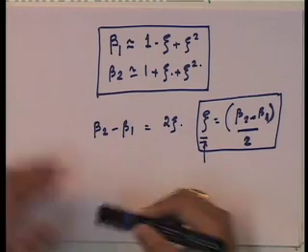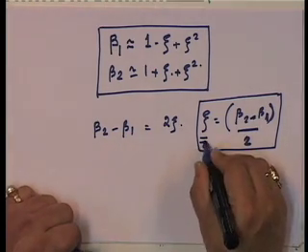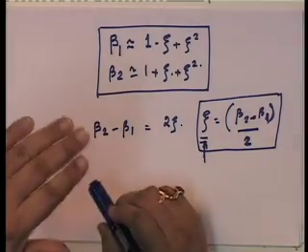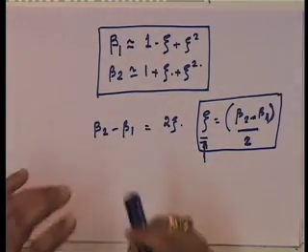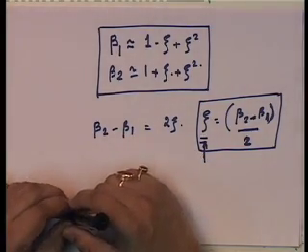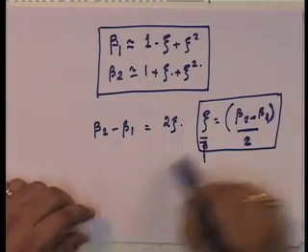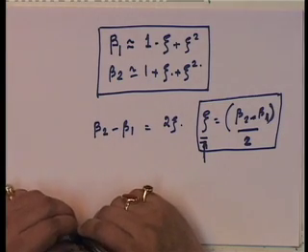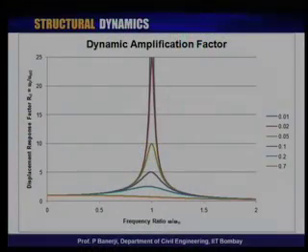So, that is where the name half power bandwidth method comes from, and this gives a very stable xi. Also, because you are at half power, you do not get sufficient feedback, so you can estimate those values fairly accurately. Those values can be measured fairly accurately, and getting the xi from there is a very easy procedure. So much for estimation of dynamic characteristics.